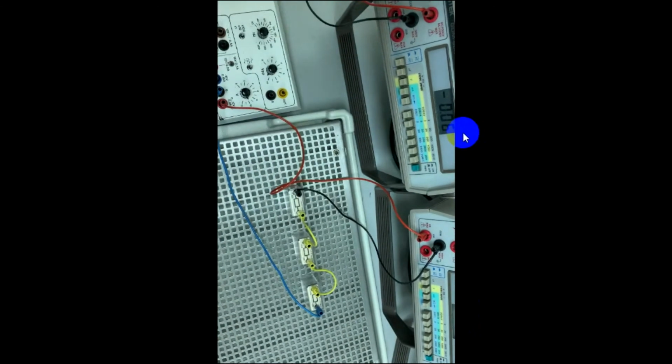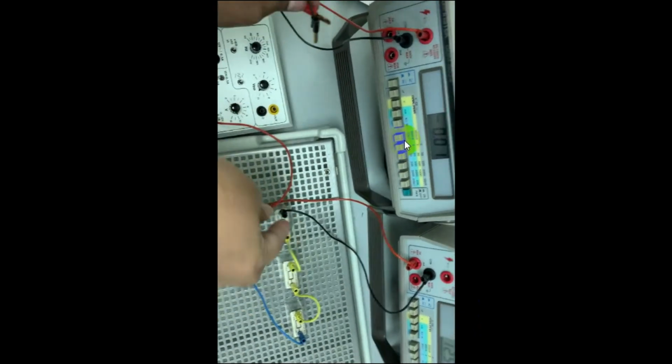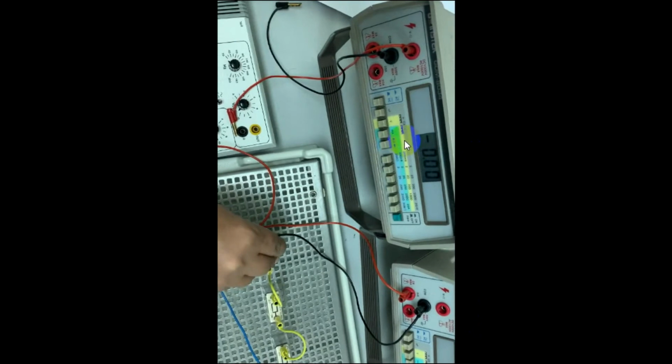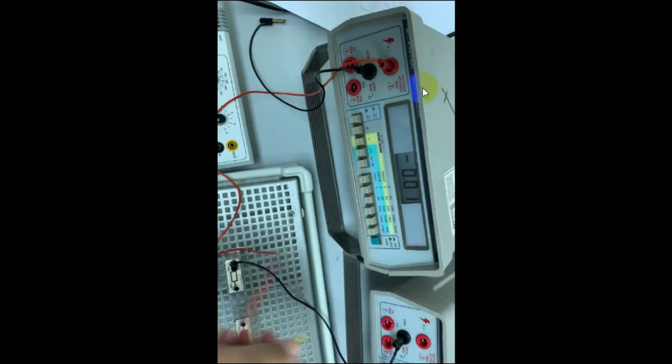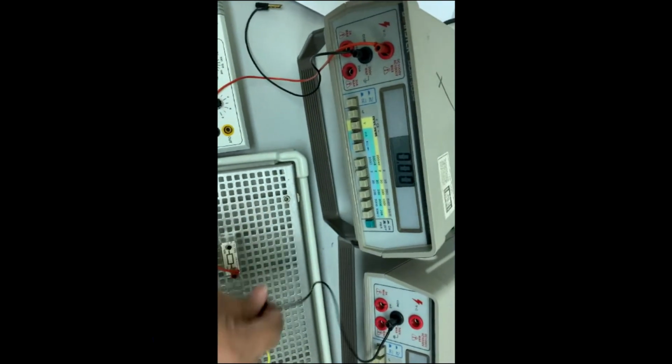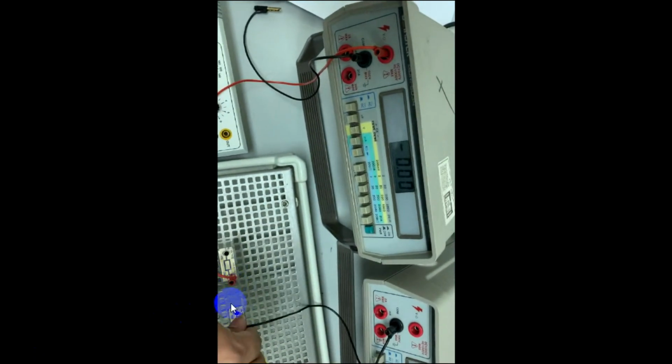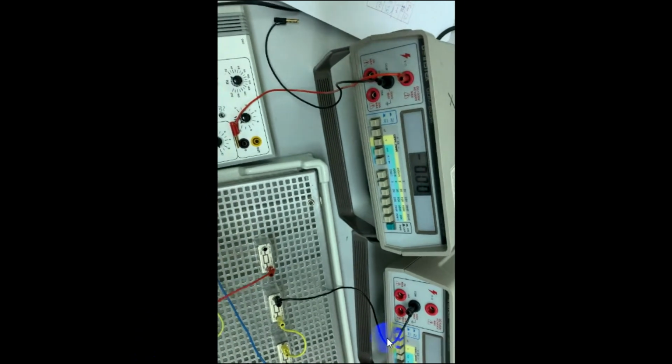So now what we are going to do is connect the second ammeter in between R1 and R2. I have to remove these two series connections and put the ammeter in between, and then see what the change in the current is. Here it was 12 point something. So is there any change when it is connected in series? Let us verify.